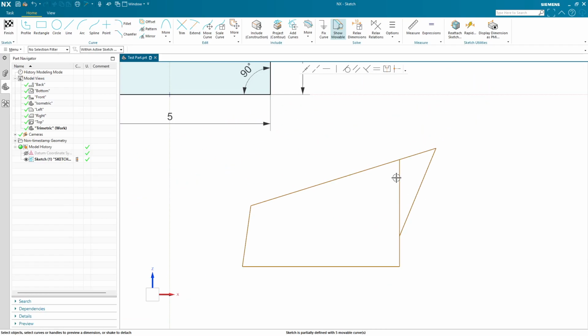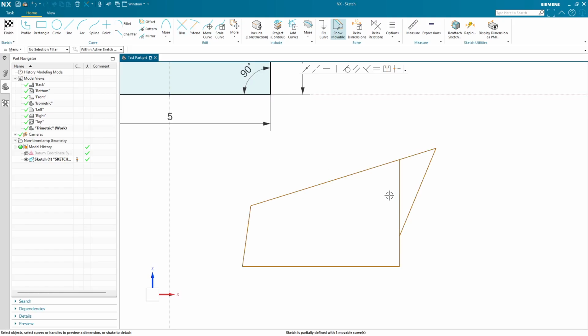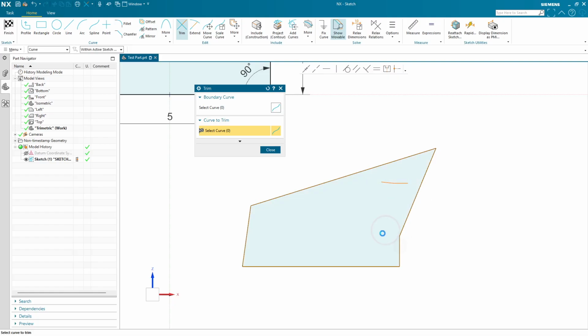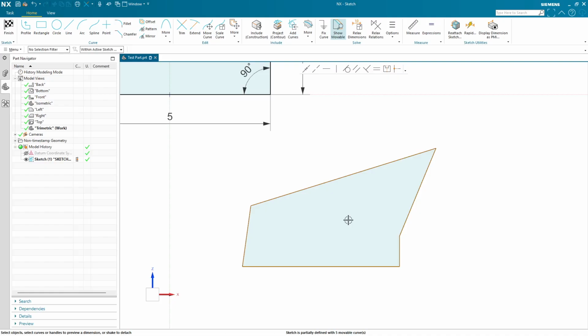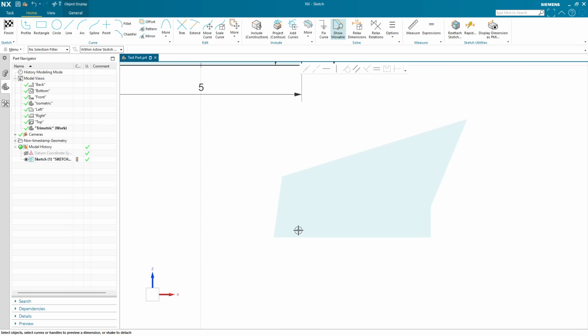So let's say we goofed and we don't want this anymore. We can go over to trim. If I click and drag, it's kind of like a hot knife through butter. Whatever this hits, that line gets deleted out of existence. Just bloop, gone. I can always press Control Z to back up a little bit if I make a mistake. But the trim tool is really handy for doing stuff like that. So that's just an example of a shape. Let's say I want to delete this. It's really simple. I'll go over here, select all of it, press delete, and then that shape is now gone.